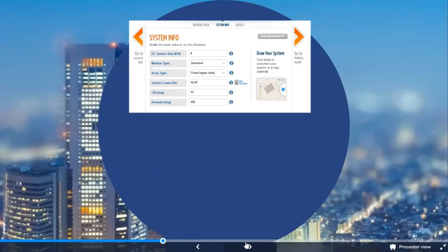You can do that also on our page. We have a tilt calculator where you type in the latitude and it'll tell you the optimal winter angle. The goal is not to have to maintain these every season. So you set it to the winter angle, and in this case it would be about 15 degrees, since they're just north of the equator. Then the azimuth degree.